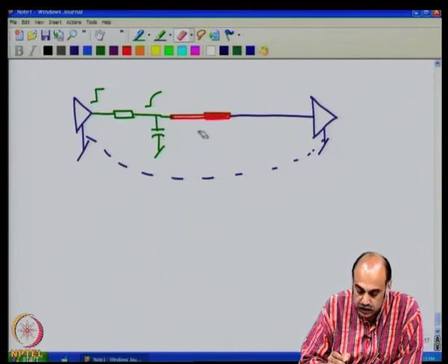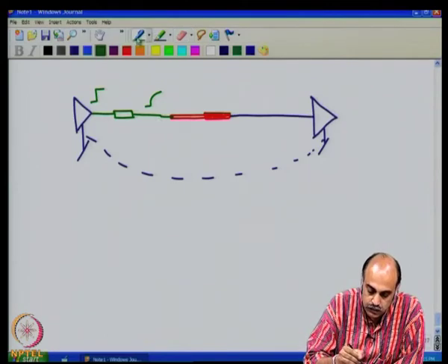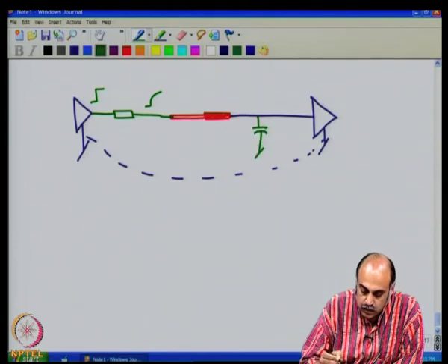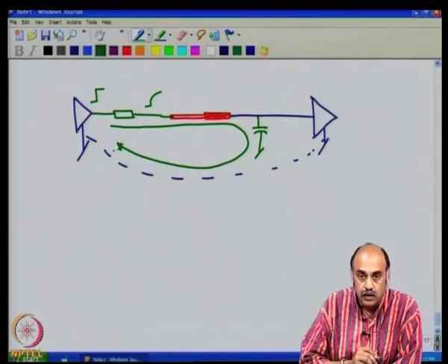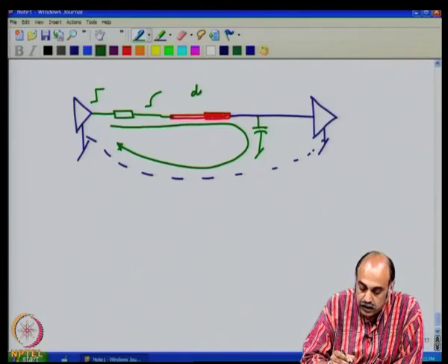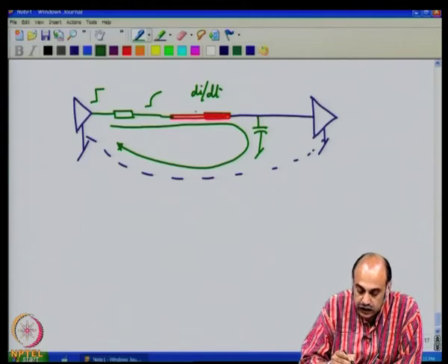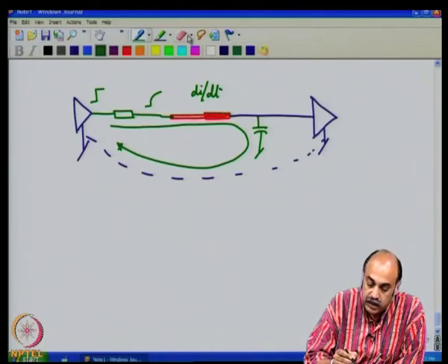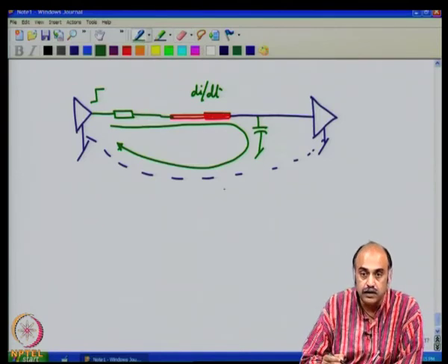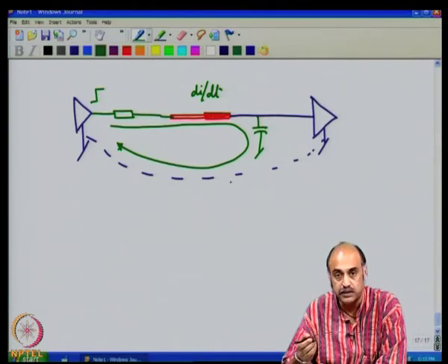However, keep in mind that you can do it this way, and when you are going about it, be careful: do not put the capacitor on this side, because if you put the capacitor on this side, then you are still having a pretty high loop area. Not only that, you are passing the high dI by dt currents through the connector, and connectors can act as antenna and radiate EMI, inducing electromagnetic interference to other circuits.